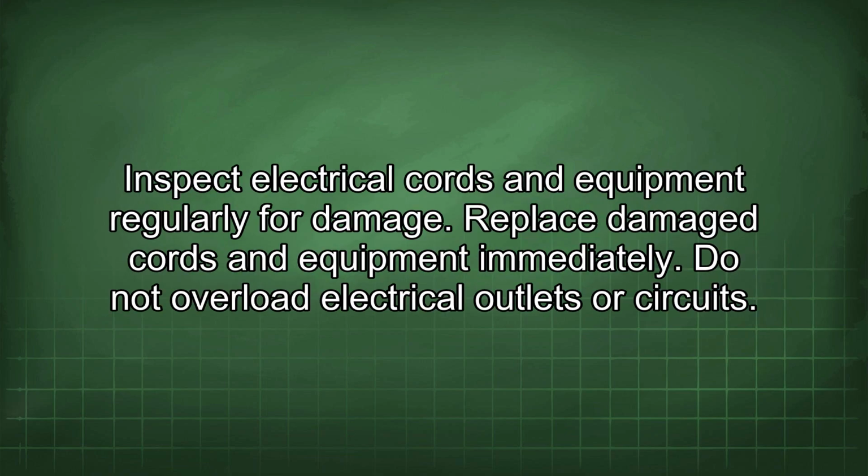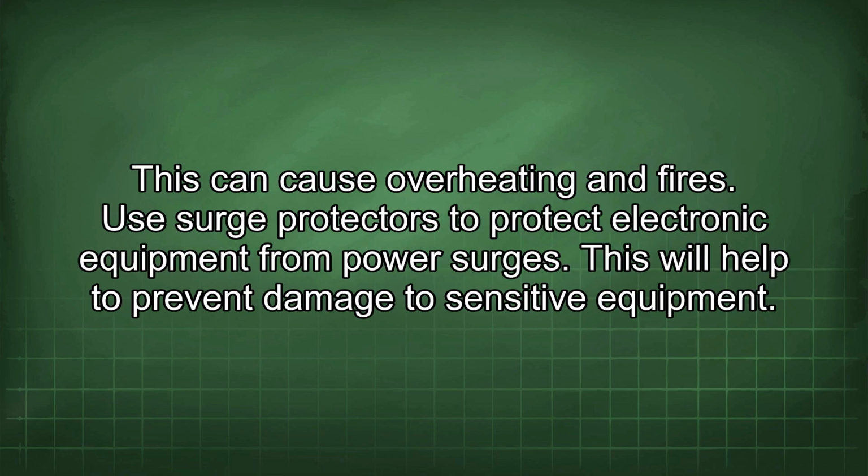Inspect electrical cords and equipment regularly for damage. Replace damaged cords and equipment immediately. Do not overload electrical outlets or circuits. This can cause overheating and fires. Use surge protectors to protect electronic equipment from power surges. This will help to prevent damage to sensitive equipment.